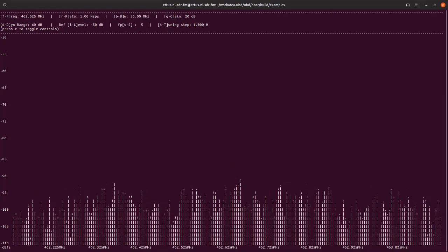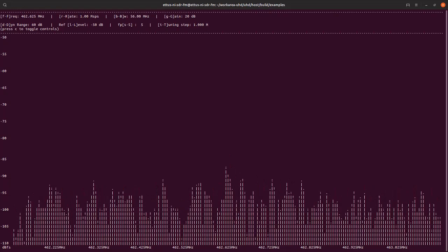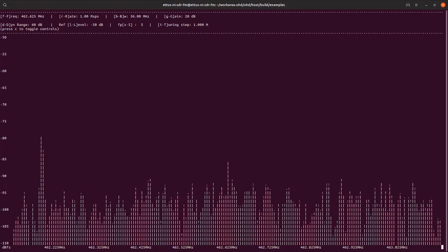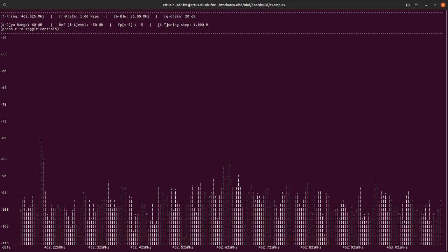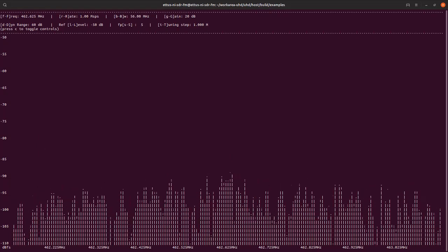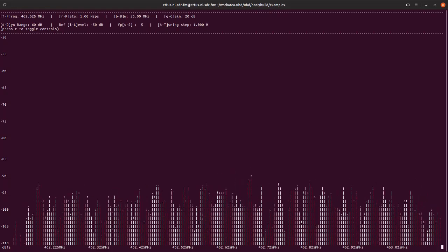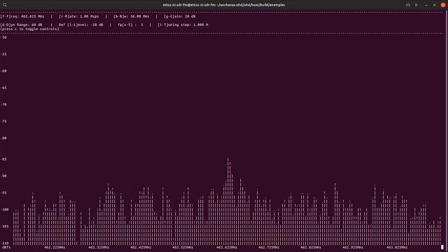I got version 3.14.1 installed in the USRP hardware driver. I built it from scratch right out of the repository, and I downloaded FPGA images, and I installed the driver, and I'm running some examples. From this point, we can go into the C++ driver, and if we wanted to, build our own application out of that.